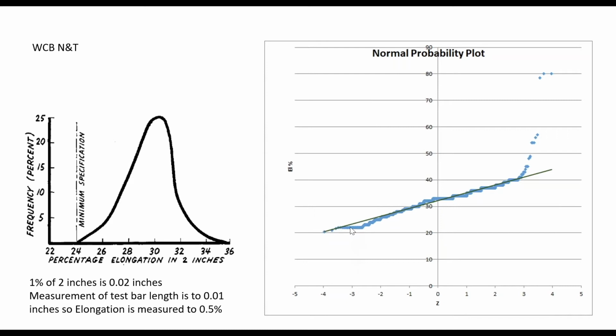So if I was really going to set the minimum capability of this data set, I would get rid of everything under 3 standard deviations, and I would eliminate all of the minimum specification stuff. But this also means that the specification takes into account the distribution of properties. And so it says that if I get a measurement that's down here and I remeasure it and get a measurement that's up here, the measurement up here can count, because the measurement I took to begin with may have been in this part of the distribution, and if I remeasure it, I get higher.